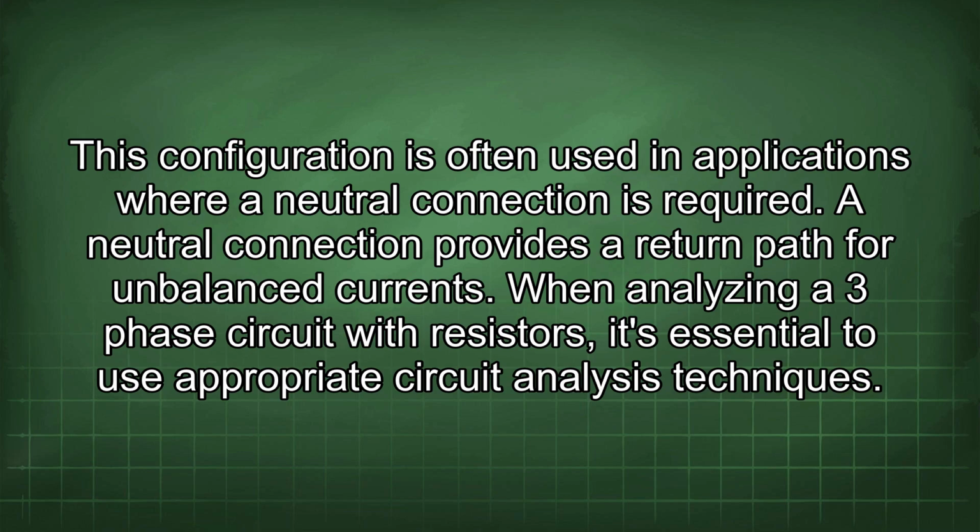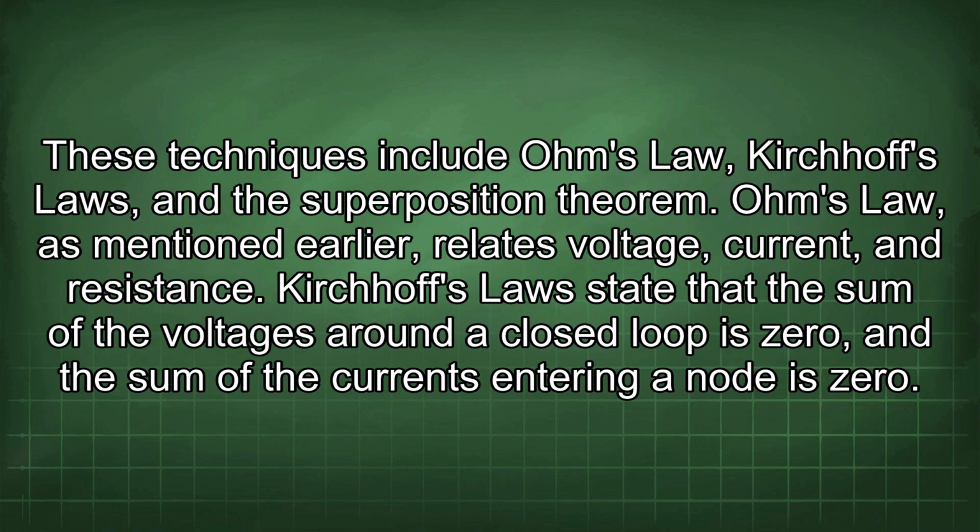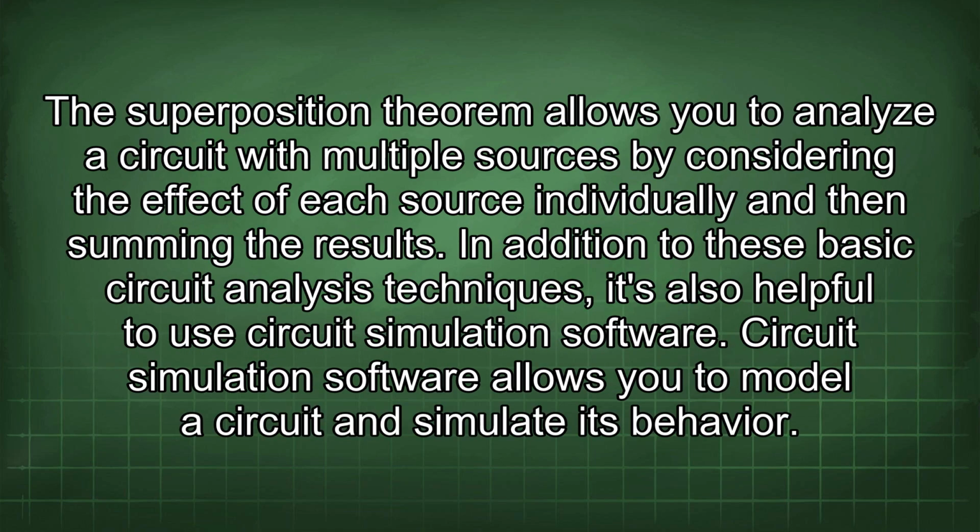When analyzing a three-phase circuit with resistors, it's essential to use appropriate circuit analysis techniques. These techniques include Ohm's law, Kirchhoff's laws, and the superposition theorem. Ohm's law, as mentioned earlier, relates voltage, current, and resistance. Kirchhoff's laws state that the sum of the voltages around a closed loop is zero, and the sum of the currents entering a node is zero. The superposition theorem allows you to analyze a circuit with multiple sources by considering the effect of each source individually and then summing the results.